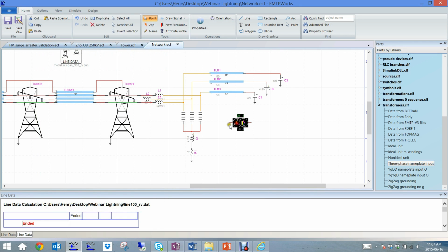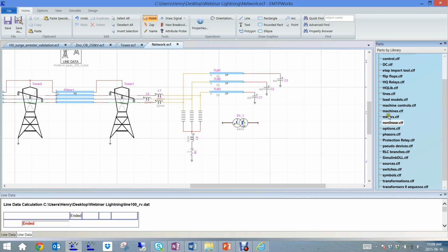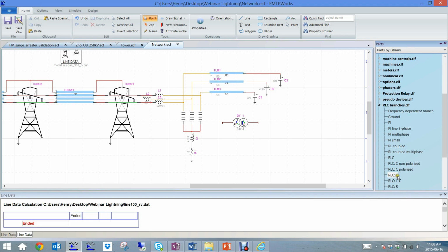But what is more important is definitely the stray capacitance. So I try to put some typical values here, but again, the most precise approach would be to do measurements or to ask the manufacturer. It's tricky, it's hard to find those data, but it's kind of the only way. Another way is to use more advanced models. For example, you can use a state space device or a high frequency equivalent model, but all that is tricky and it's not really the point of today's webinar.